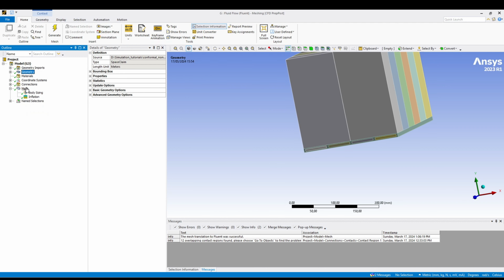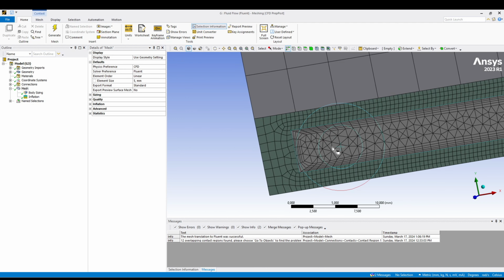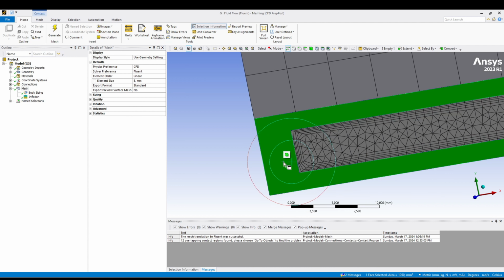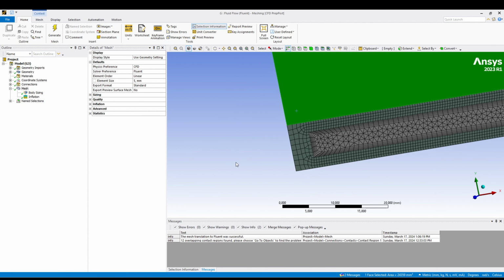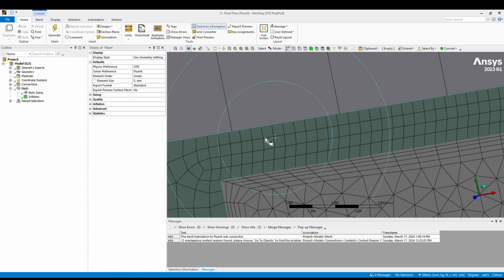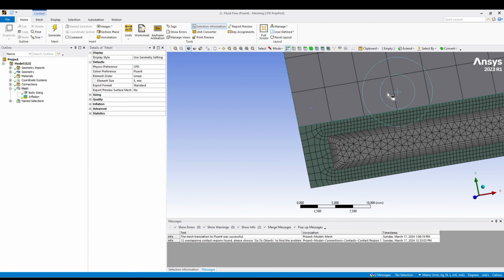First of all, here is our meshing. It is our fluid region. This one is our base plate and these are our battery cells. You can see nodes are not shared between different regions. Here is one thing: you can use a really coarser mesh for the solid region and a finer mesh for the fluid region. This meshing is helpful when you have limitations from computational power.